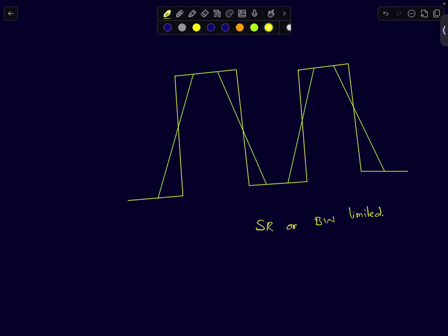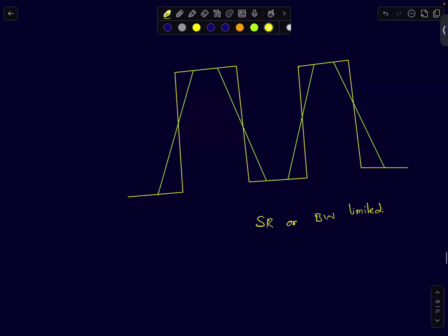and differentiators. So first, you are given a waveform like this. This happens to be the waveform at the output of an amplifier circuit. So now a question was asked, can you, by looking at the waveform, say, assume that this is an inverting or a non-inverting amplifier. Okay, there is no frequency dependence in the circuit, but the op-amp is non-ideal. By looking at this waveform, can you say whether it's slew rate limited or bandwidth limited? What can you gather from this waveform?